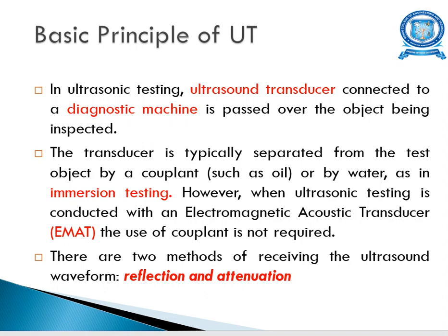And the basic principle of ultrasonic testing: an ultrasound transducer connected to a diagnostic machine is passed over the object being inspected, and the transducer is separated from the test specimen by a couplant such as oil or water, as in immersion testing. However, when ultrasonic testing is conducted with an electromagnetic acoustic transducer, a couplant is not required.